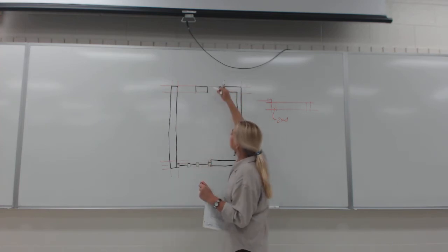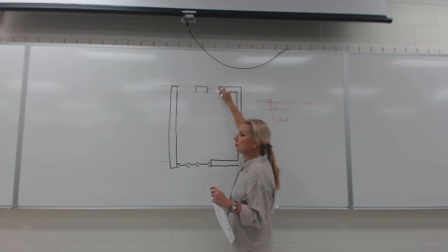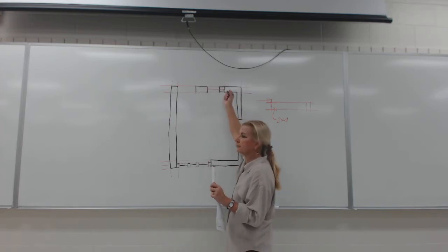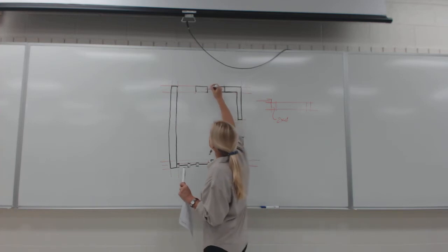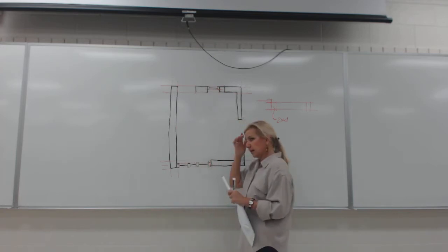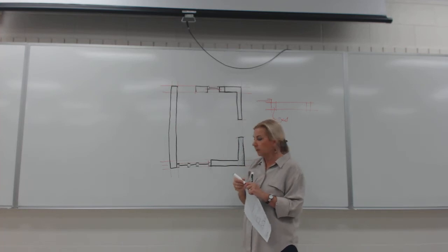So again, you would use a light construction line, and you know what? You can eyeball that too. Time is precious. You don't have to measure half. You can probably see it. And then you would draw boxes like this and the line. So that's windows. The door is a slightly different story and a little bit more complicated.